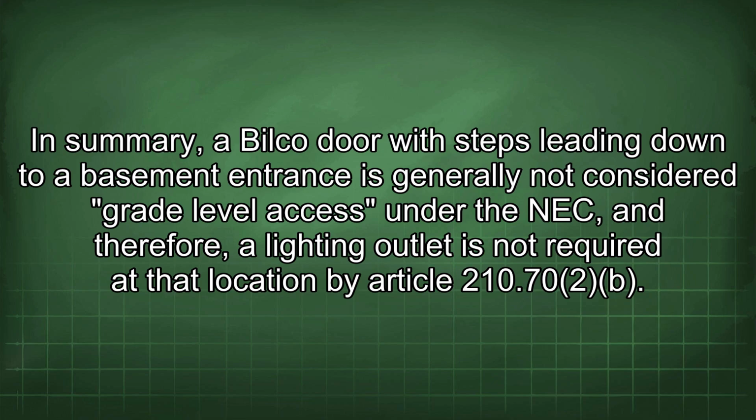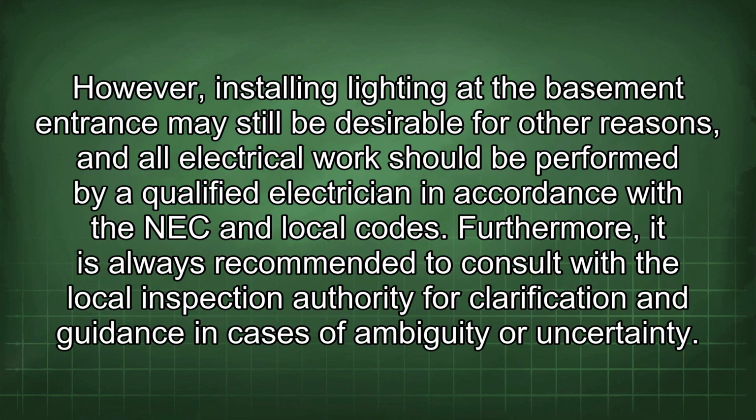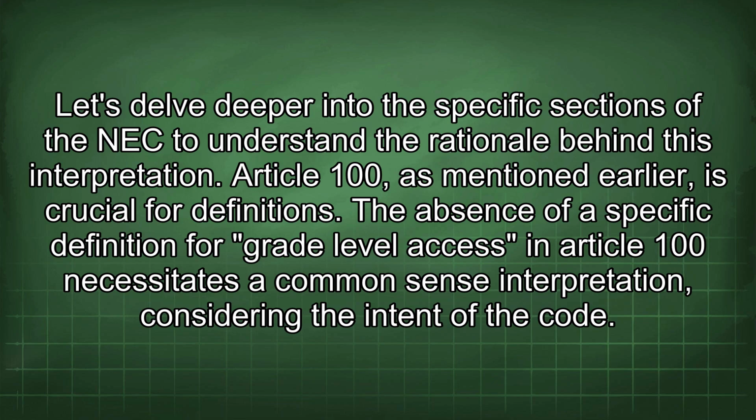In summary, a Bilco door with steps leading down to a basement entrance is generally not considered grade level access under the NEC, and therefore, a lighting outlet is not required at the location by Article 210.70. However, installing lighting at the basement entrance may still be desirable for other reasons, and all electrical work should be performed by a qualified electrician in accordance with the NEC and local codes. Furthermore, it is always recommended to consult with the local inspection authority for clarification and guidance in cases of ambiguity or uncertainty. Let's delve deeper into the specific sections of the NEC to understand the rationale behind this interpretation.